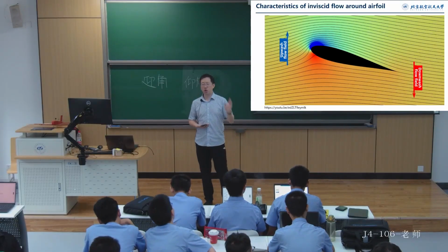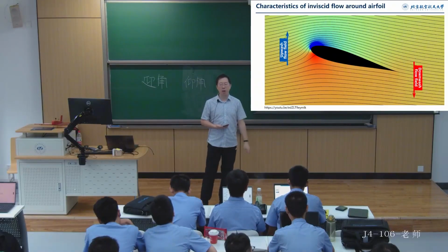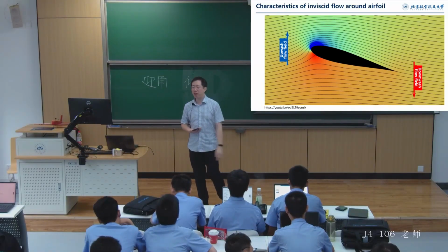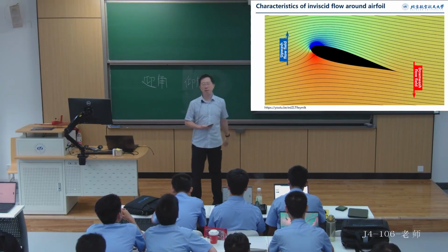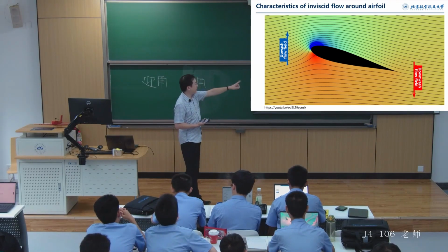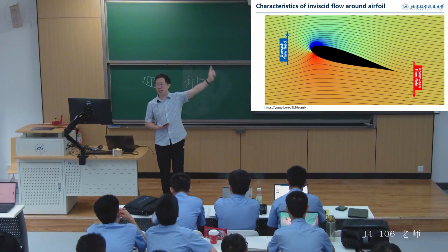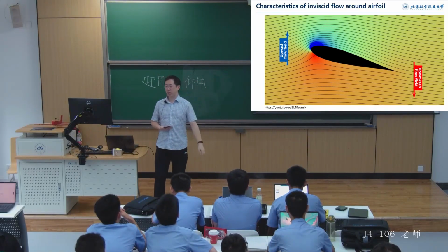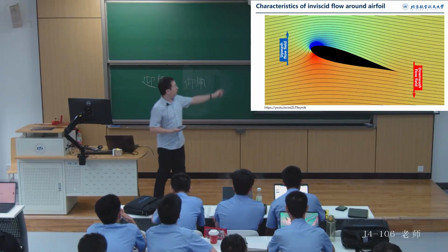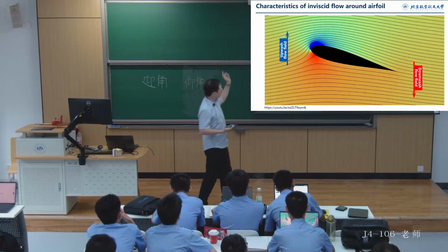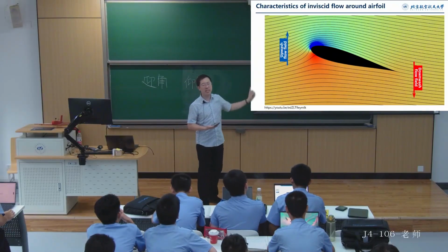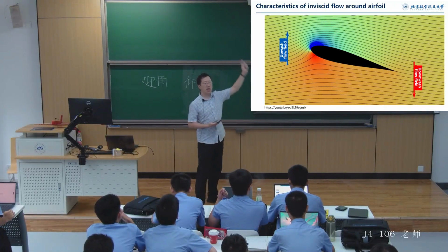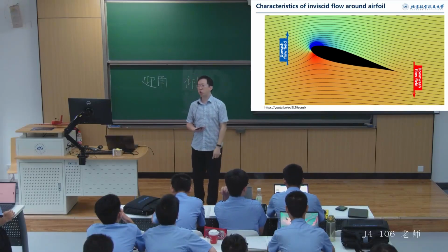This indicates that the momentum of the air has changed. And what can cause a change in momentum? Only a force can cause a change in momentum, right? So that means an upward lift is generated on the wing, correct? Because forces always come in pairs. By changing the airflow from upward to downward, a downward force is applied to the airflow. Naturally, the airflow then applies an upward force to the wing, or the airfoil. This is the momentum theory we use to explain lift.